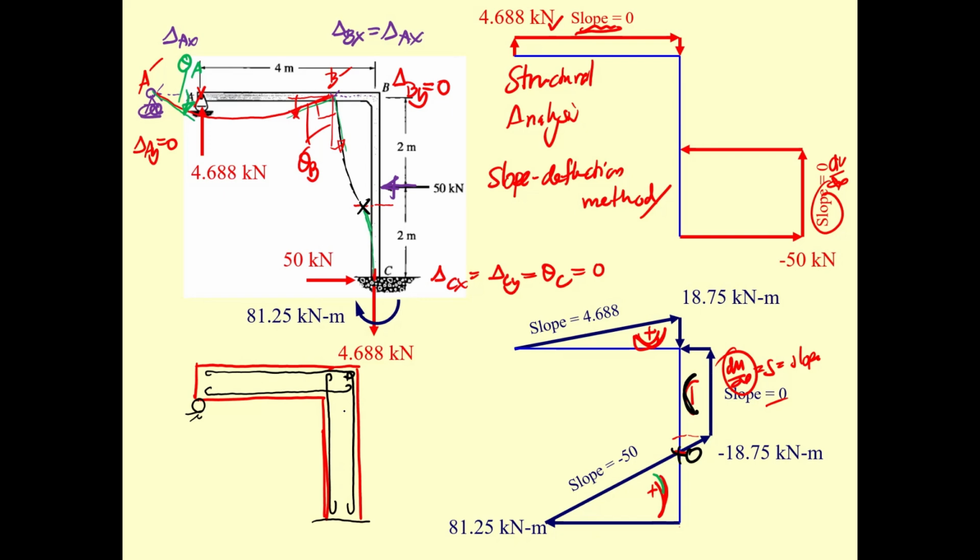And now, due to the positive moment over here, you may put more reinforcement in this portion, sorry, at the bottom over here because the moment over here is large. And then for this one, you should put it over here. And then for this one, you should put it over here. This is the sketch in your head.